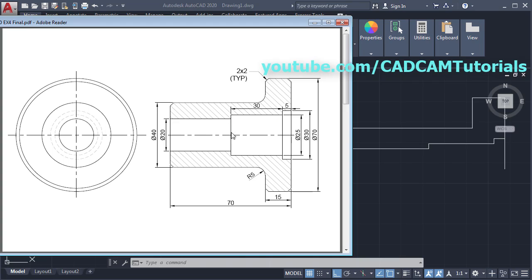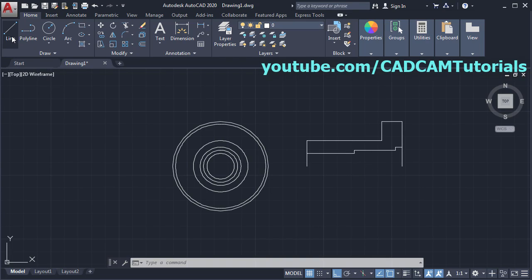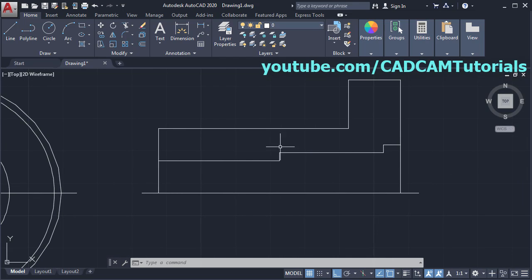We will just extend these lines. For that we will create this horizontal line. Click on line, then take your cursor to this quadrant and take it outside and click. Then click here, enter, enter. Then take your cursor to this endpoint and take it outside, click, then click, press enter, then zoom it. Then to extend, take your cursor to this arrow near the trim and click on extend. Then press enter. Then click on these lines on the lower side.